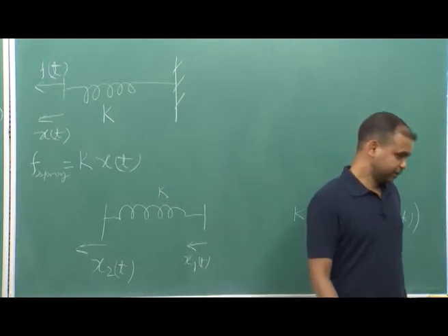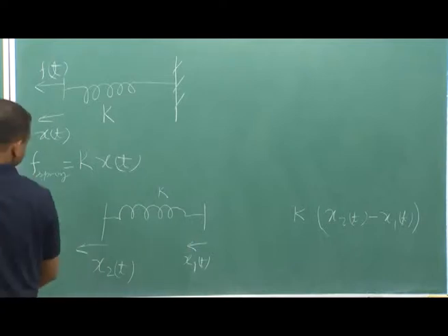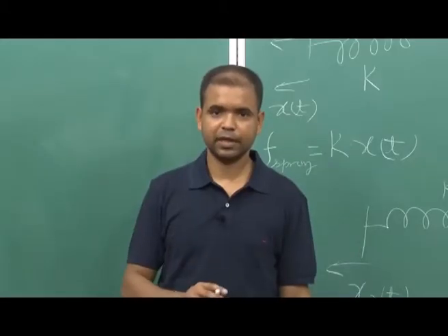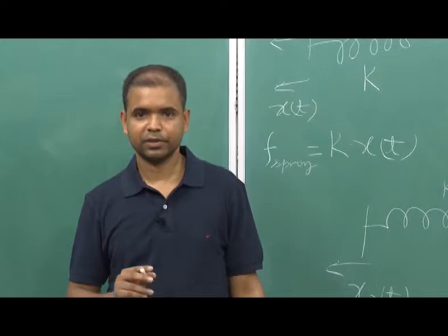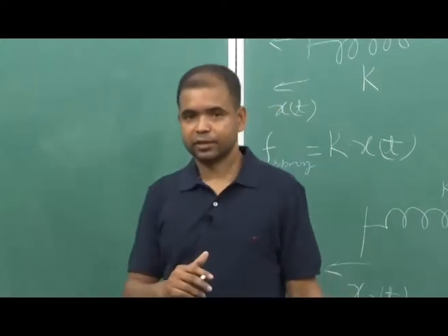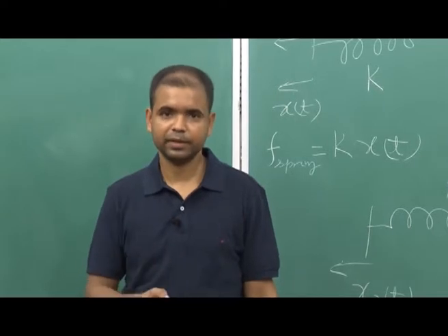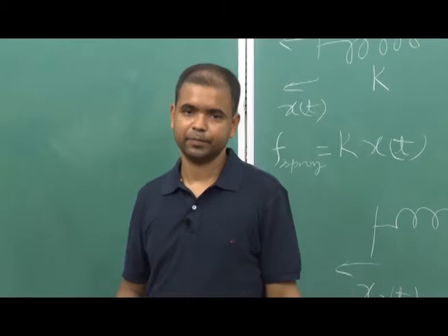The spring is also conservative in its nature, and it stores the potential energy of the system. So, the spring and mass are both transferring energy to each other with a phase difference of 90 degrees, but you can see the energy is conserved throughout the process. So, if there is a spring mass system and you deflect it, it will continue oscillating because there is no energy dissipating element.